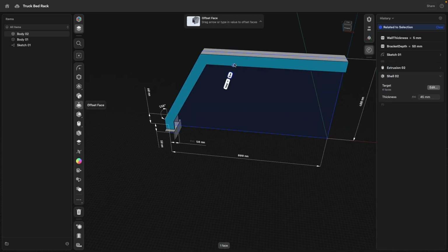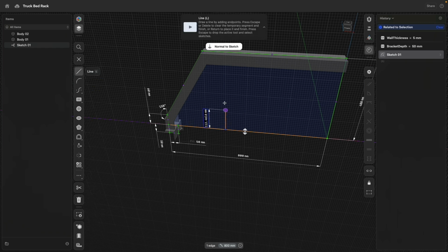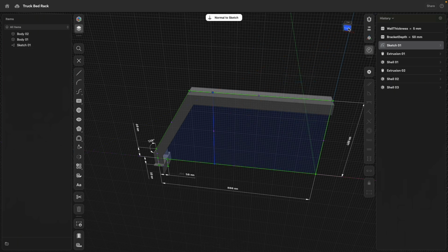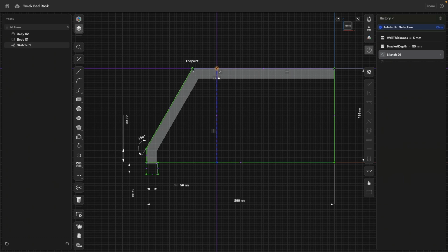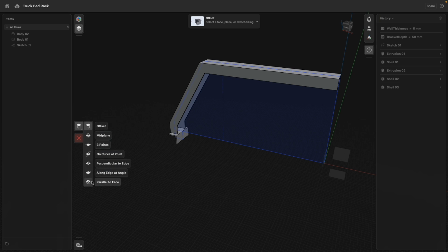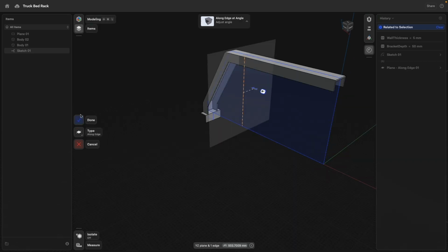In the next step, we need to block this one out into two pieces and then also create a material offset and an overlap. And this is also where the variables come in very, very handy. So I go back to the sketch and somewhere here draw a straight vertical line. Right click, drop the line tool, go to a side view, construction and horizontal, vertical aligned. This line should be 100 millimeters. I can keep this in the sketch so it's easy to see. And then I will create a construction line along edge. This one to this plane and click done.